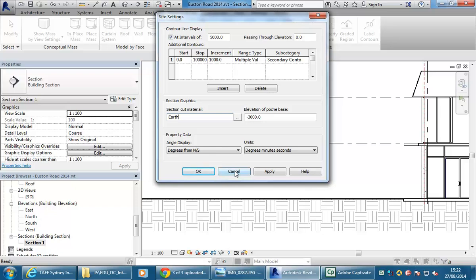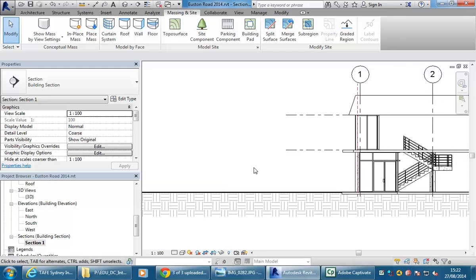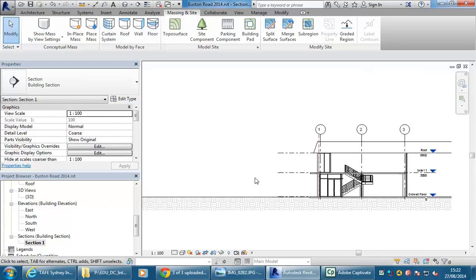But you could have had the image on wireframe when building the site. Yep. And lowered it by another -10 for the footpath, -20 for the road. Oh yeah, if you want to do it like that, you can. Yeah, absolutely. If you wanted to see it in section, like where the street is. That's right, you can. So I can still do that now because it's all still the one ground surface. Because it might be appropriate for like a basement apartment. Exactly. So for this project, I don't think you need to show that detail, but it's a good idea for some others. Yeah, definitely.